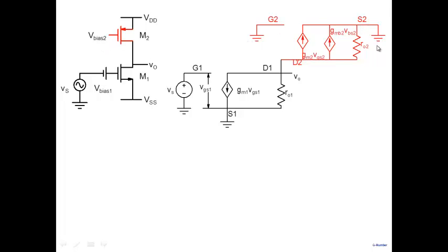And so this is the model for M2. And note, in a PMOS, we'll always assume that the source is tied to the body, because each PMOS transistor can be made in a separate well. It doesn't show here, but the body here is tied to the source. So this particular current source becomes 0. You can ignore it and you are left with this particular one over here.